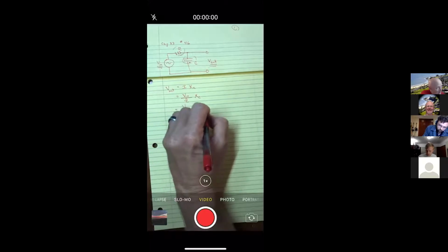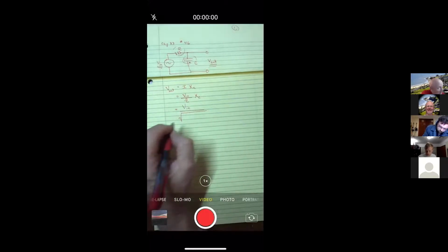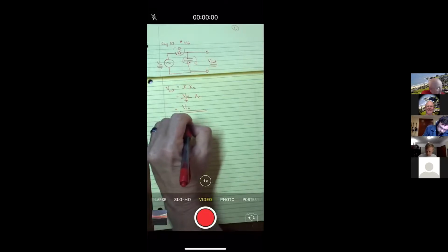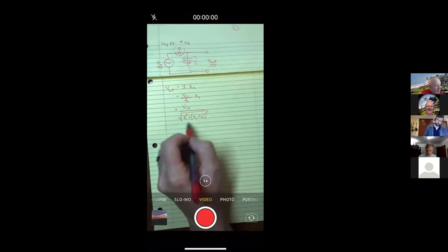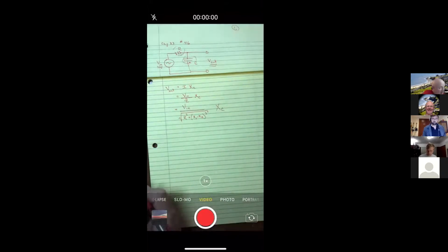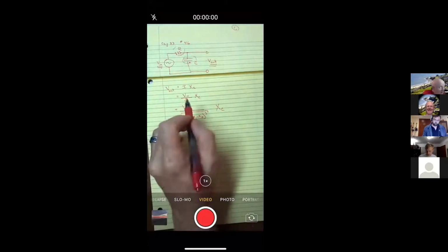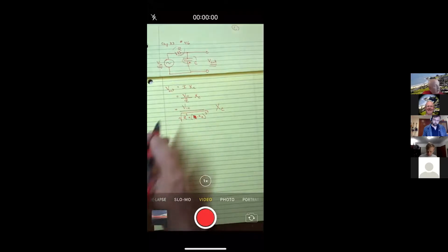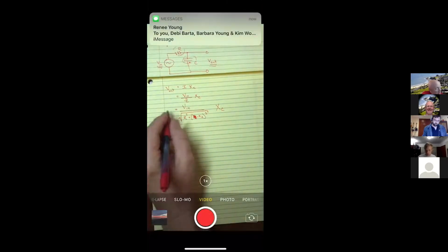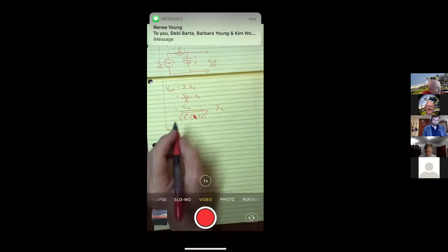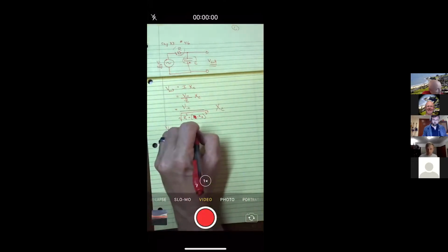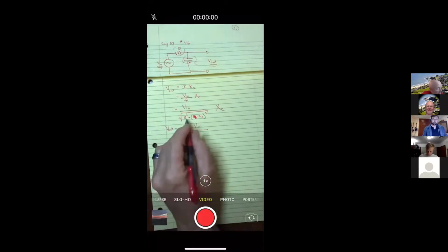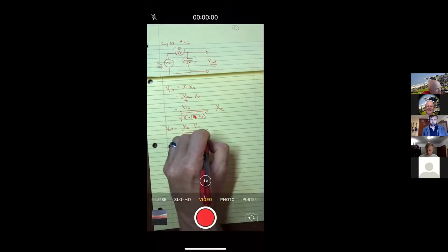And the calculation for the impedance was pretty involved, so I'll just cut right to the derivation of it. We had the square root of R squared plus (XL minus XC) squared. That's the impedance. And of course, for this one, there is no inductor, so I might as well just cross that one out. So this would say that the voltage I get out is then equal to, and I'll just switch the order here, XC, the reactance of the capacitor, times the voltage you're putting in, divided by the square root of R squared plus the reactance of the capacitor squared.